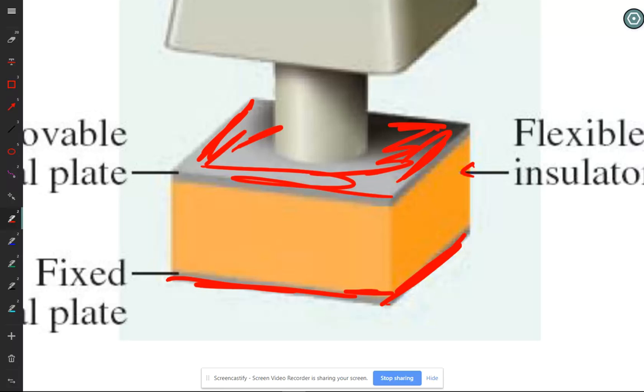Because it's epsilon 0 times kappa, kappa being the dielectric constant, something that tells you how good that insulator is at making an electric field, actually. Times area of the plate divided by the separation. As the separation gets smaller, the capacitance goes up. So when you press that key, the capacitance goes up. And kappa will probably go up a small amount too, but we ignore that for this problem. So if the capacitance goes up, what's going to happen? Well, they put a constant voltage on that key. So you have something like 5 volts